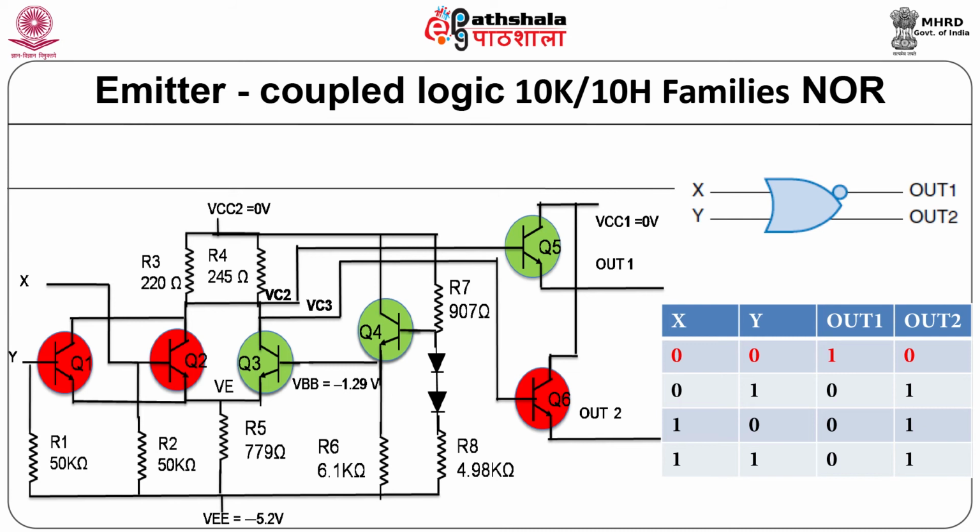The packaged components in today's most popular ECL family have 5-digit part numbers of the form 10xxx. This family is called ECL 10K. This family has several improvements over the basic ECL circuit, as it has an emitter follower output stage that shifts the output levels to match the input levels. An internal bias network provides VBB without the need for a separate external power supply.